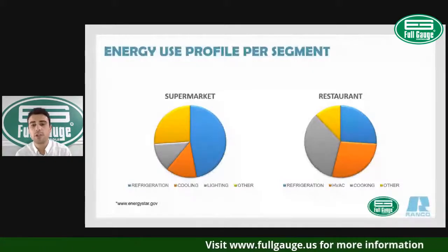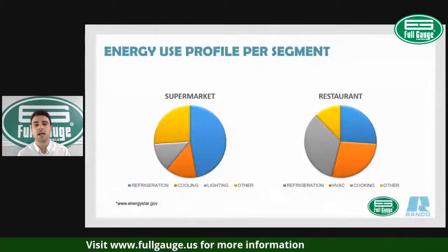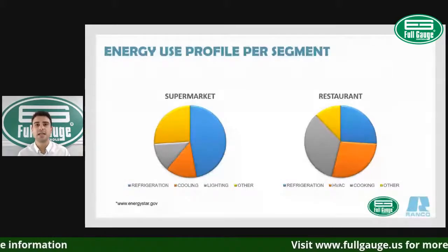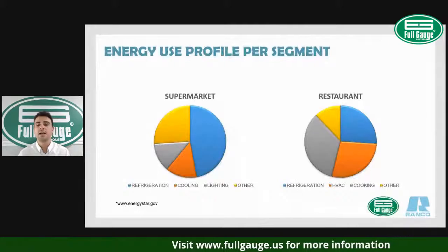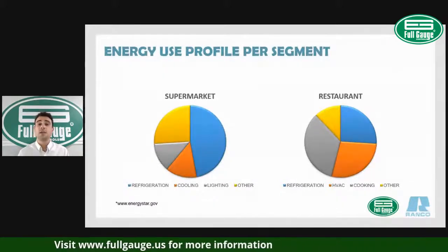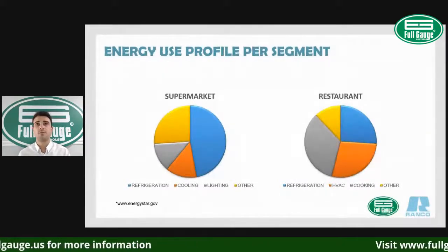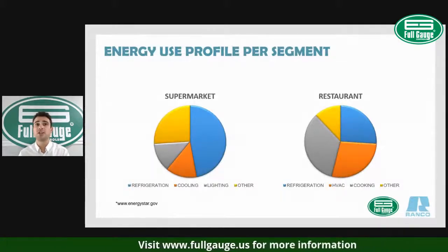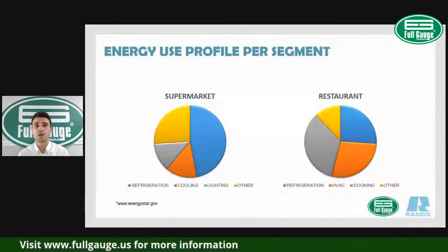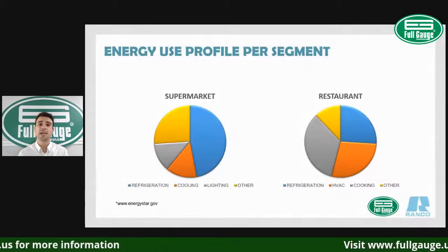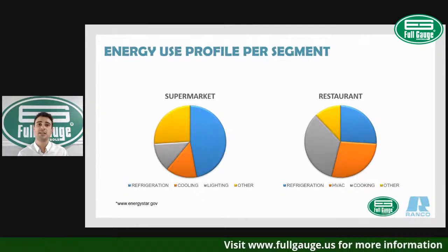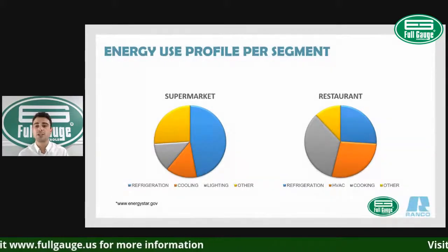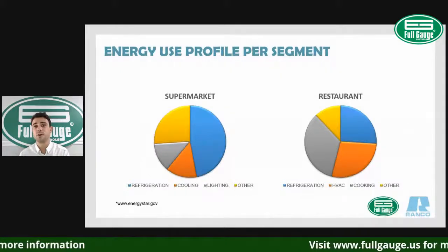For example, when we look at time defrost, when you have a time-initiated, time-terminated defrost or a time-initiated, temperature-terminated defrost, you're running defrost every 4, 6, or 8 hours, but you don't know if the defrost is actually needed during that frequency. We have studied the on-demand adaptive defrost technology in an application where we optimized 90% of the defrost cycles.